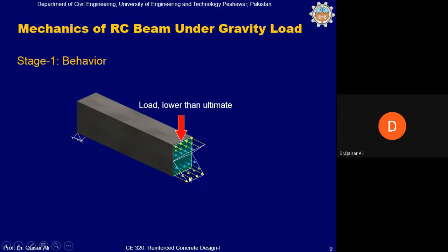Okay. Now, the upper part of the beam has a triangle with the maximum compressive force in the upper part of the beam, and then the stresses decrease gradually till they become zero at the neutral axis, and then tensile stresses are produced, and tensile stresses keep on increasing till the bottom fibers of the beam, and they are maximum in the bottom fibers of the beam.